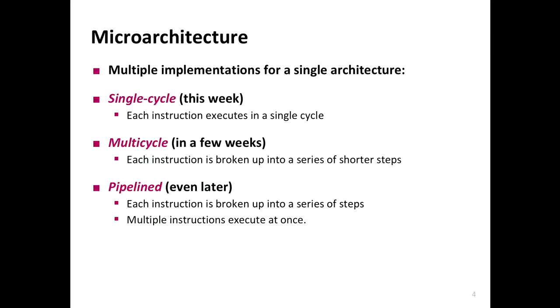to solve dependencies. For example, if you're going to do an add followed by a multiplication operation, and you need the result of the previous operation for the add operation, you need to somehow check for these dependencies and do some reordering and things like that. You will actually be seeing all these things later in the multi-cycle and pipeline architecture. So there's much more logic that has to be implemented as we go multi-cycle and pipelining.